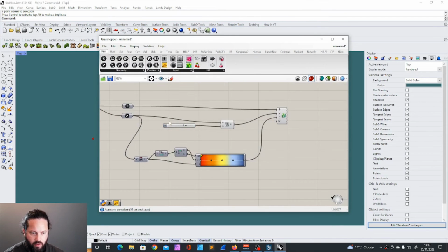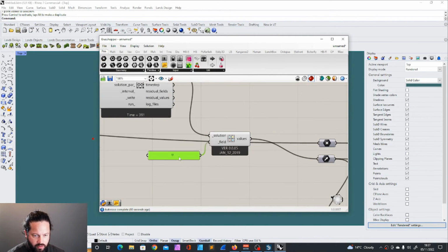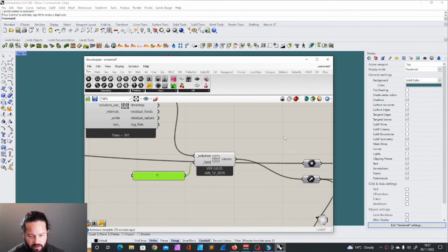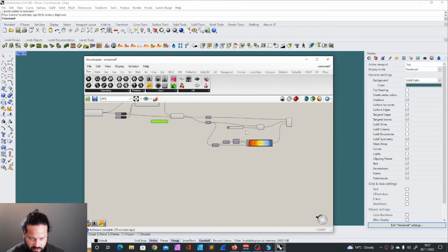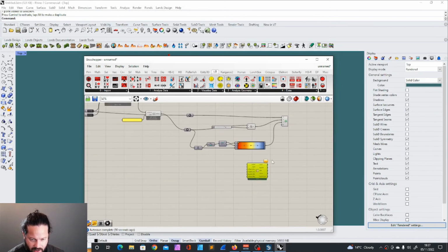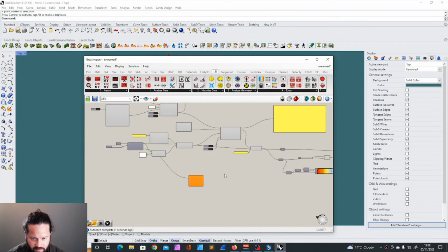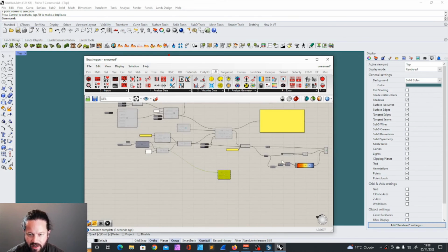So now another way we can deal with it is if, for example, we would have the pressure, we could also calculate the pressure and then add a heat map to it and look at the heat map output of that same mesh. I'll just show you what I mean by that. So we could have here a Ladybug spatial heat map. That is actually just a mesh, representing the mesh. This is a mesh output. This was created for us. And then we could add our values.